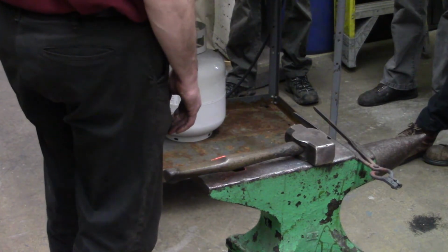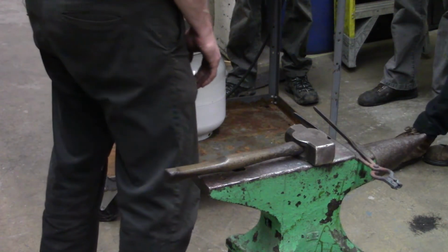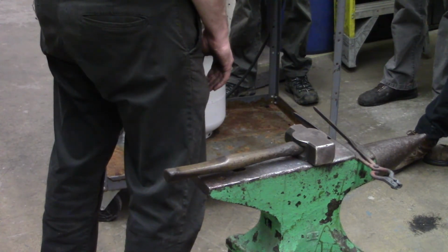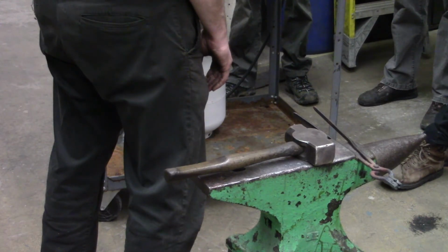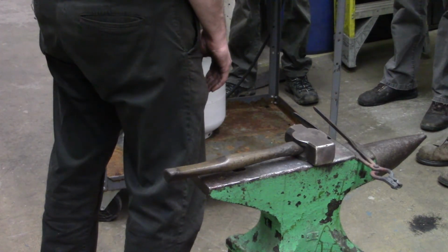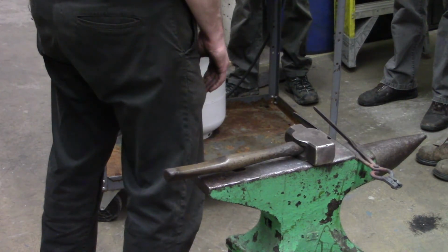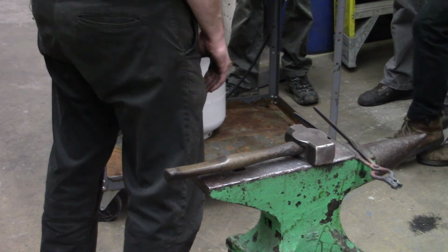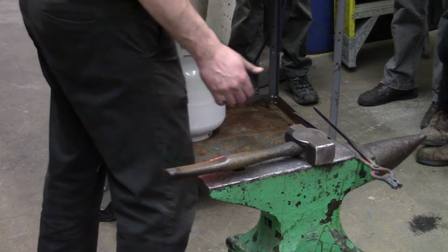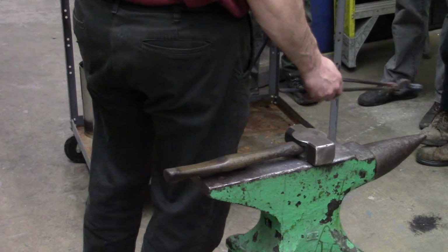I had a Firebird with T-tops, so it was like my trunk and hatchback basically. It's basically a solid metal box right over your gas tank and axle. So you just pull up the carpet, cut a hole, replace the fuel pump, go back in. And that was about an hour and a half fix instead of days. Yeah, wow.